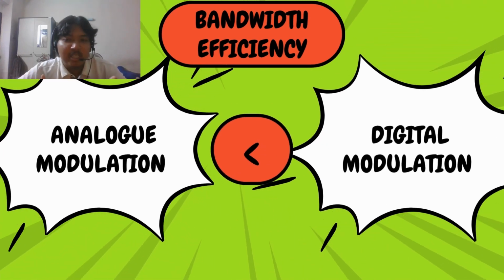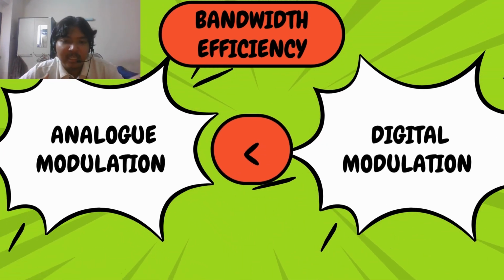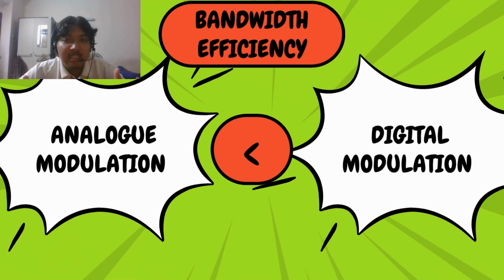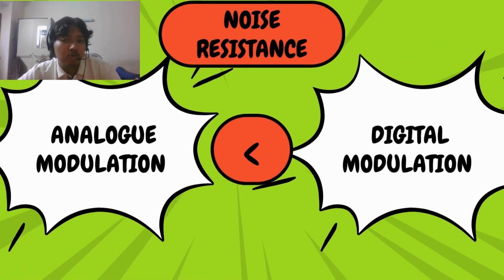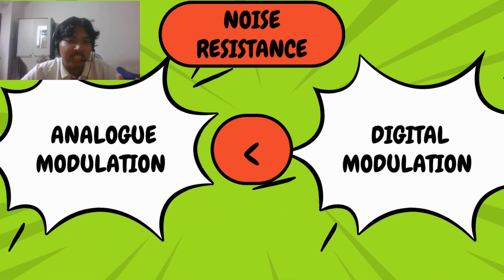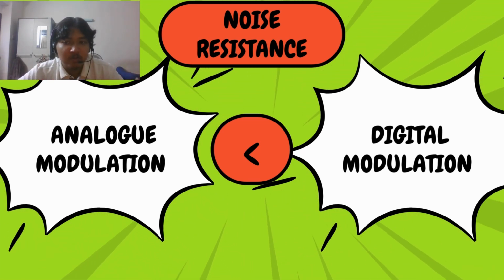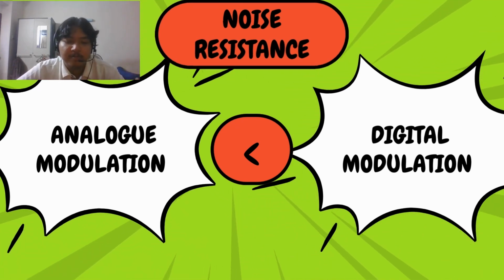Analog modulation requires more bandwidth compared to digital modulation. This is because digital modulation can be packed more densely, which allows it to have a higher data rate even when using the same bandwidth as analog modulation. Analog signals are more exposed to noise interference than digital signals. Analog signals represent data in a continuous nature, while digital signals represent data using discrete values in binary form. So an analog signal is more prone to being affected by noise interference.